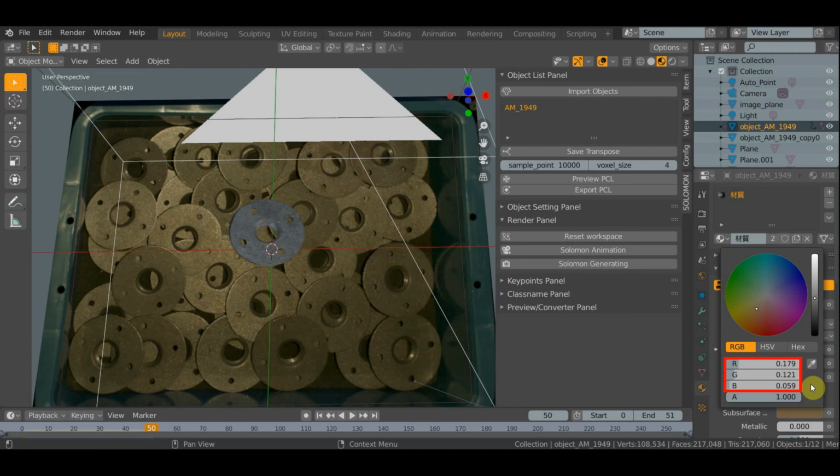In my case, the texture of my object has an image of the real object as surface, so it doesn't matter what RGB color the surface has. The CAD model will always display the image as the texture, but if your CAD model doesn't have an image as texture, then I strongly suggest you change the RGB to 0 as it was by default, because having the real color of the object already incorporated into the CAD model in addition to a light that displays the same color will strongly influence the way the color of the objects will appear in the simulation.